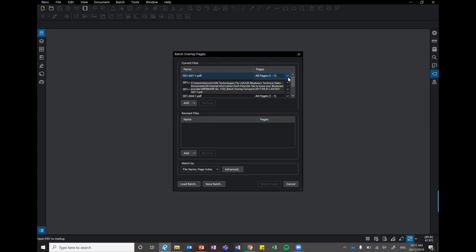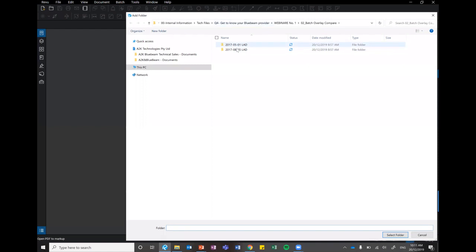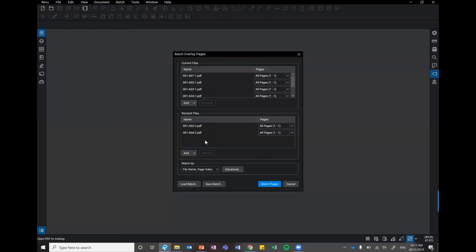You might receive 50 shop drawings, but sometimes got sheet 1 of 2, 2 of 2, or even up to 3 or 4 pages at times. I go through into the folder. I'm going to pick the next revision and have this compare. Interesting enough, we have several drawings in here, up to 5. And we only have 2 drawings in here. So we don't have to go through the file itself and compare apples and apples. We can have apples and oranges as far as quantities.